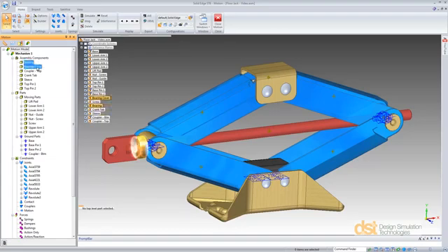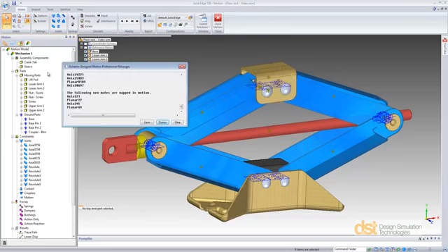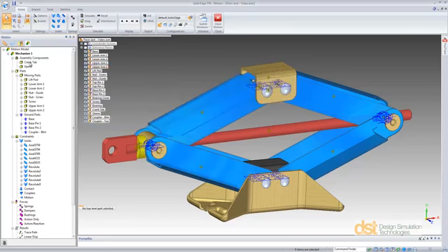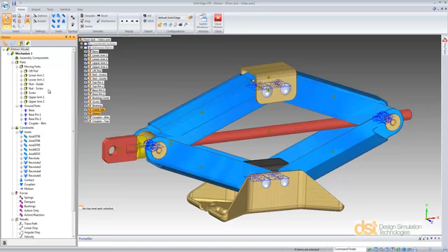We'll select the bearing and the bearing cover, and we'll rigidly attach those to the guide nut. The top coupler and the two top pins will be rigidly attached to the lift pad, and then finally the crank tab and the sleeve will be rigidly attached to the screw.